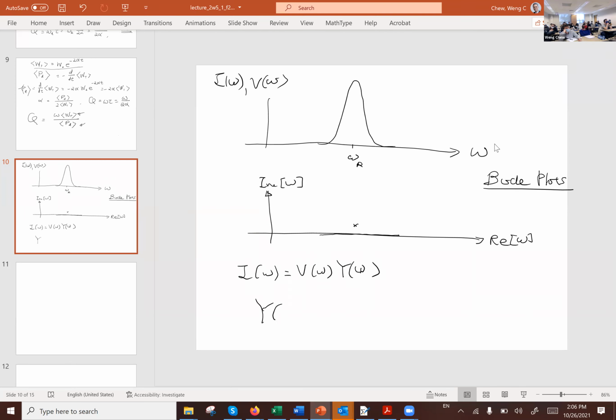From a very simple viewpoint, this transfer function can be approximated with a simple pole approximation, where omega_r is actually that complex number over there. You can see that this function never quite goes to infinity now. If you operate on the real omega axis, you will never encounter that infinity, and hence this transfer function is never infinite.